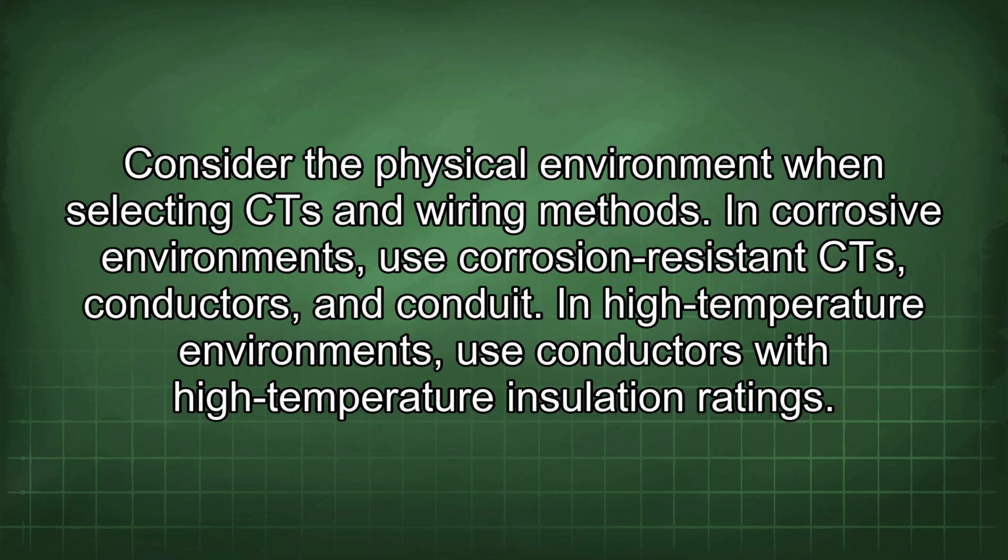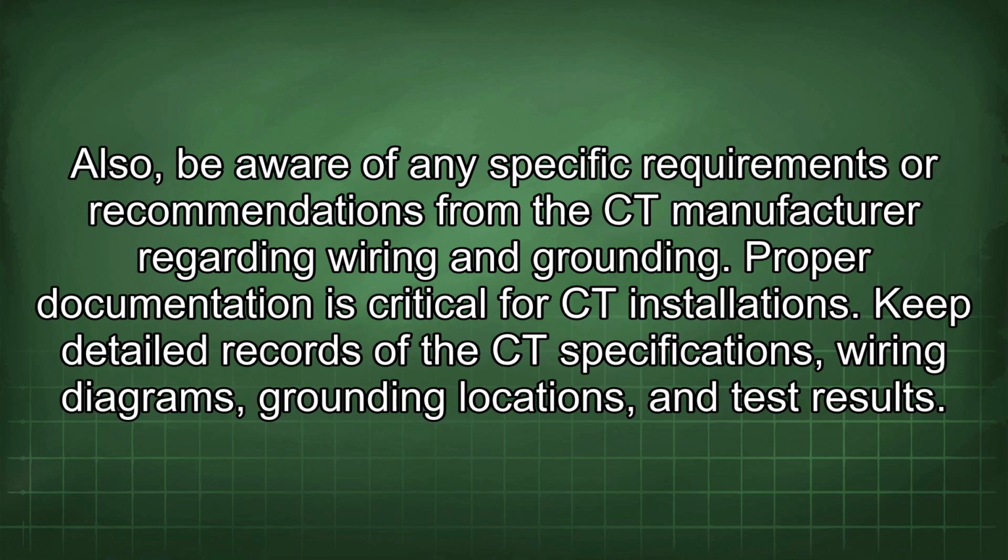In corrosive environments, use corrosion-resistant CT, conductors, and conduit. In high-temperature environments, use conductors with high-temperature insulation ratings. Also, be aware of any specific requirements or recommendations from the CT manufacturer regarding wiring and grounding.